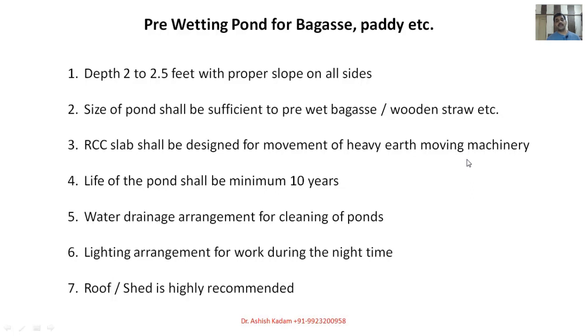We have seen many times that people are not doing the right foundation, the right pitching, they are not putting the right filling material to make the foundation for the RCC slab, and after 1 or 2 years they see huge cracks, and then they spend a lot of money on maintenance.